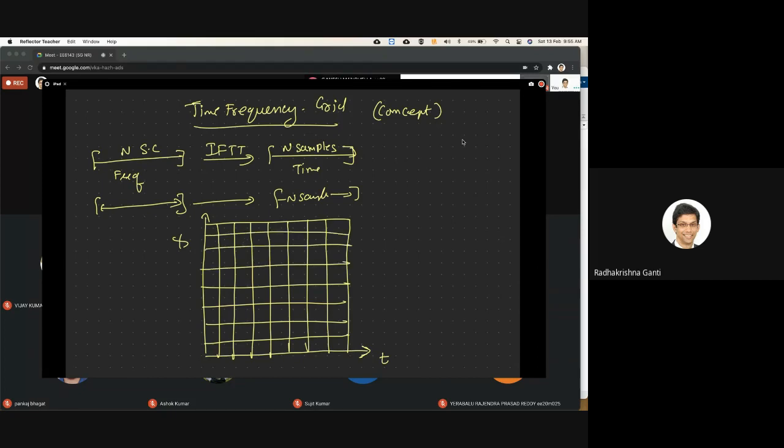Okay. So essentially, on the vertical axis, you have to think about this as just an interpretation. These are your subcarriers. This will be your zero subcarrier, depending on top or bottom. This will be your first subcarrier, second subcarrier, and so on up to the n-th subcarrier. This is your OFDM symbol. So the interpretation is that this whole thing would correspond to one OFDM symbol after you do your IFFT.